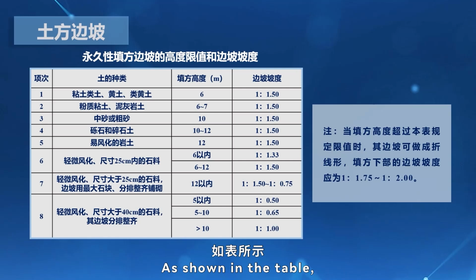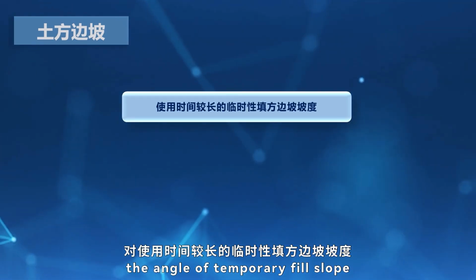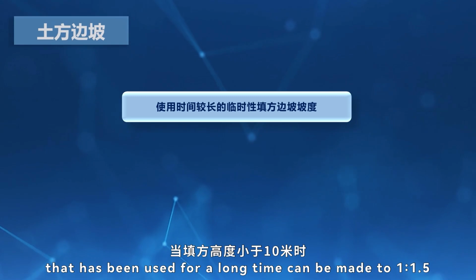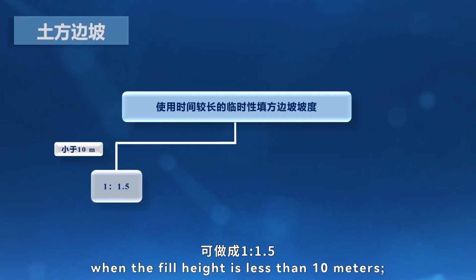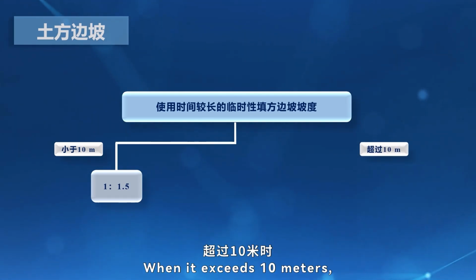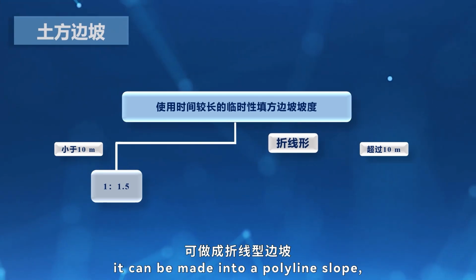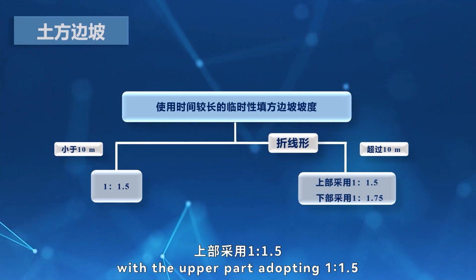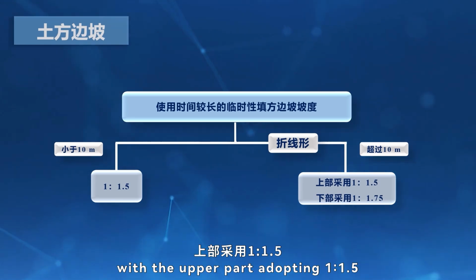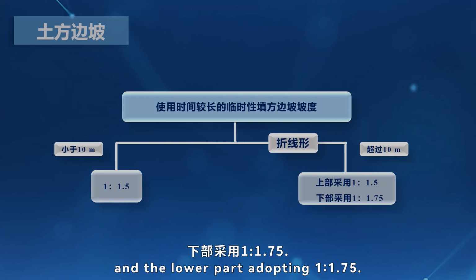As shown in the table, the angle of temporary fill slope that has been used for a long time can be made to 1 to 1.5 when the fill height is less than 10 meters. When it exceeds 10 meters, it can be made into a polyline slope with the upper part adopting 1 to 1.5 and the lower part adopting 1 to 1.75.